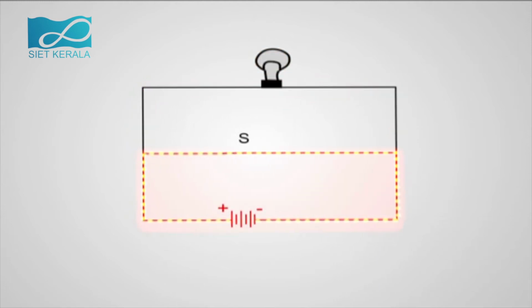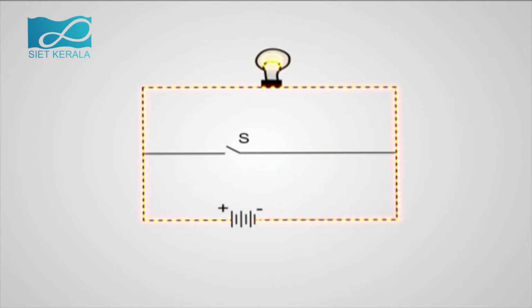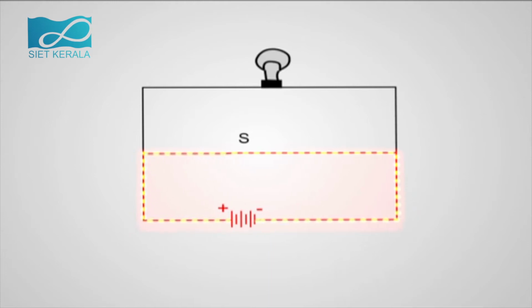When the switch below the bulb is switched on, current gets 2 paths. One through the bulb having a high resistance and the other through the switch S, which has negligibly small resistance. When switched on, the current goes through the path S, the switch which has no resistance, and does not pass through the bulb which has high resistance. Due to lack of resistance, current increases very much and the wire becomes red hot. This is what we call short circuit.